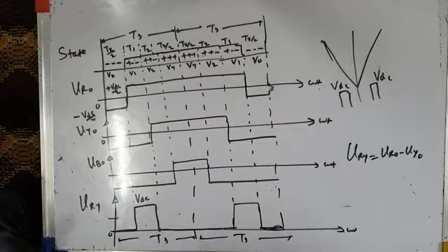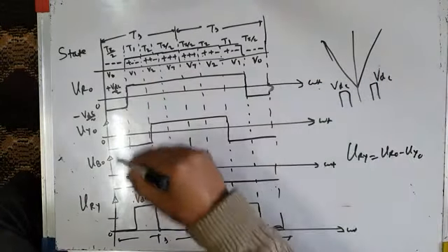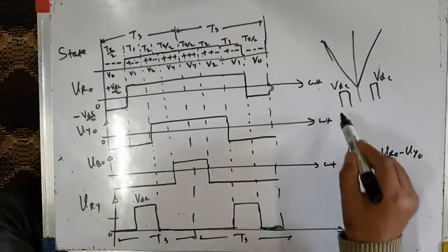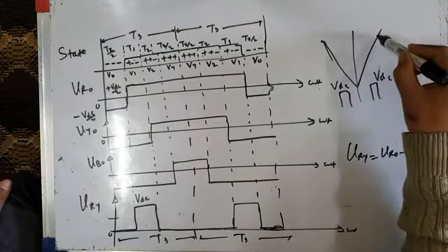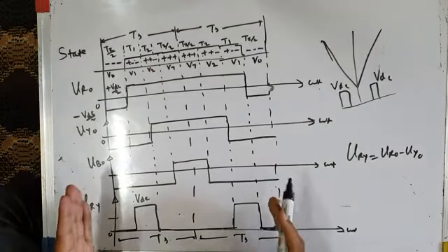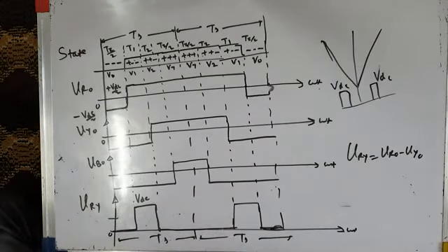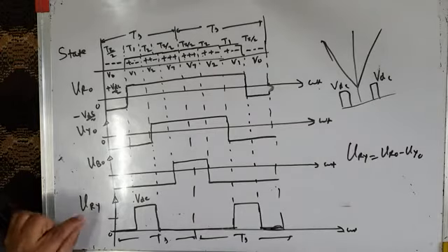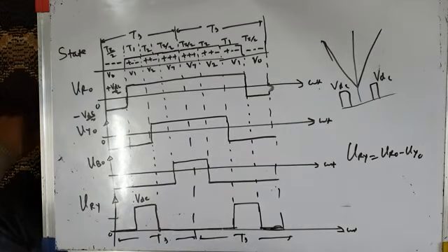So this is the comparison between the triangle comparison method and space vector based PWM. It remains the same. In the triangle comparison method, in one carrier cycle, 2 line voltage pulses are applied across the load. The same is the case with space vector PWM. In 2 sub cycles, 2 line voltage pulses VRY, similarly VYB and VBR, will get applied across the load. Right? This is the switching sequence.